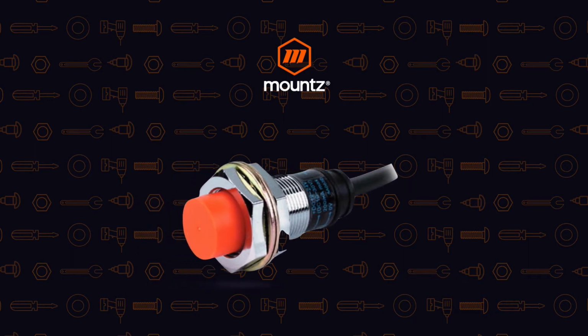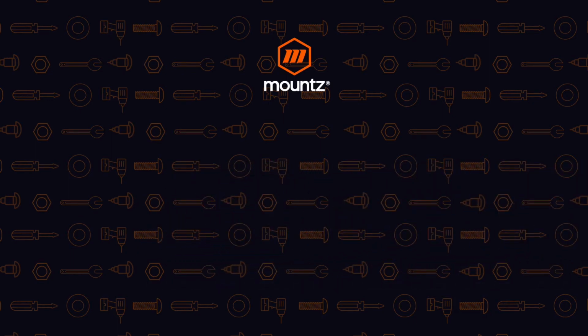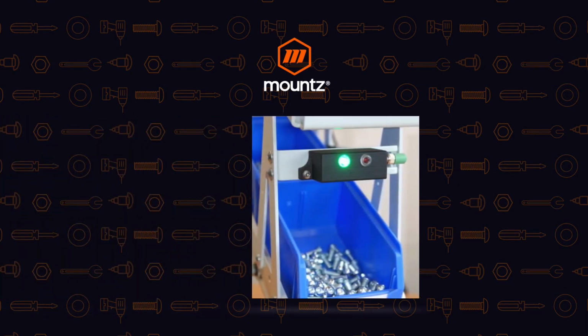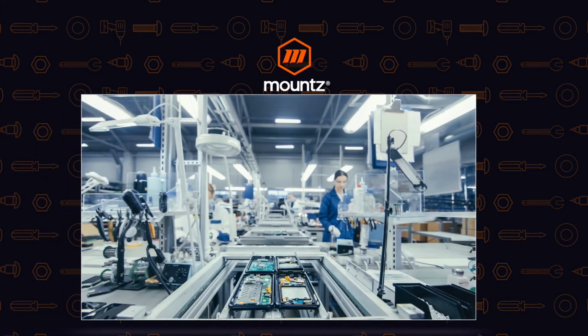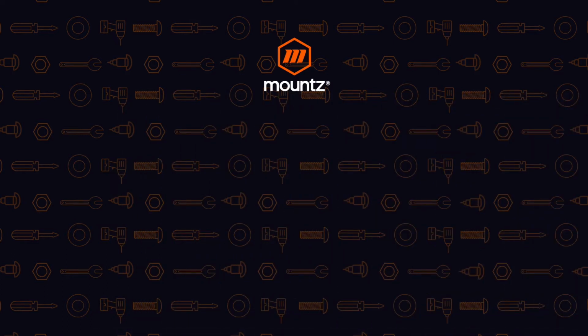We can also have proximity sensors to make sure that parts are where they're supposed to be when they are being assembled. We have pick-to-light sensors that can also be used to make sure the operator is picking the correct parts. There's part in and part out line management that we can use as well within the particular assembly process.